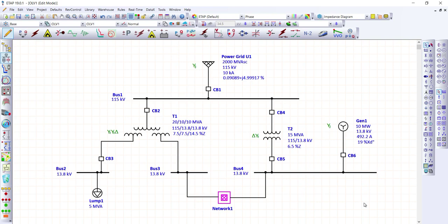But bank size, location, the capacitor control method, and cost considerations are important issues that need to be optimized during the design phase. An ideal solution would be a capacitor placement tool able to weigh all these factors, and that considers load levels.